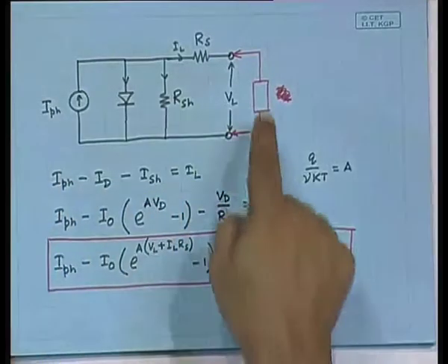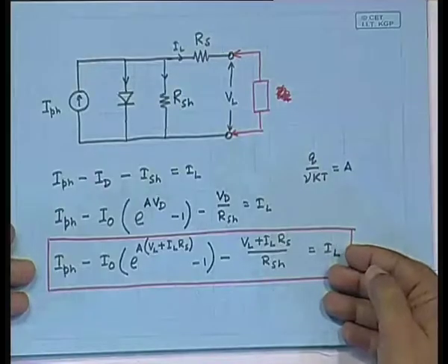For a fixed R_L, you will get a fixed voltage and a fixed current. No, current and voltage ratio does not make any sense. Current and voltage ratio is the resistance. All right. So for any fixed voltage, any fixed resistance, the current voltage ratio will be the resistance. That is okay. But the point is, this particular equation would mean that for any resistance, if you have a particular value of the voltage and the current, for another resistance you will have another voltage and current, V_L and I_L. Yes, it will be dependent on R_L. It will be dependent, but because of this source characteristics, they will not be linearly related.